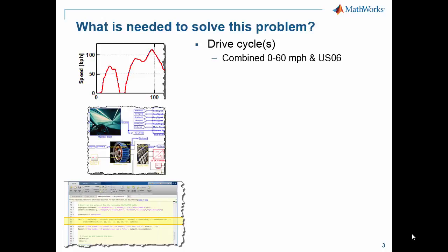This will allow me to disqualify design candidates that have insufficient performance or otherwise lead to a constraint violation with minimal simulation cost. In a more extensive study, one would likely want to conduct a robust optimization that includes multiple drive cycles to ensure that the MPGE maximization over a broad set of scenarios has occurred and mitigate any sort of cycle-beating design candidates that may result.